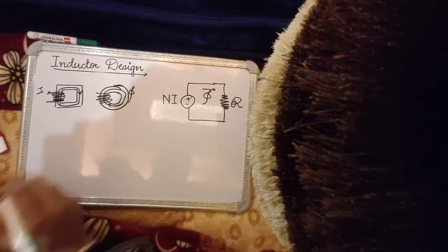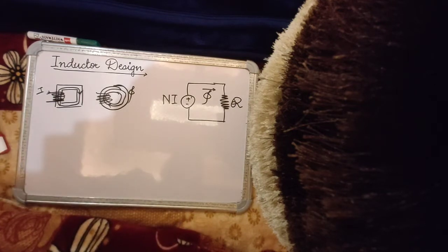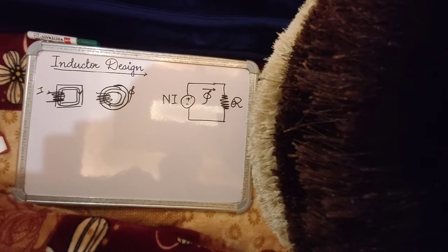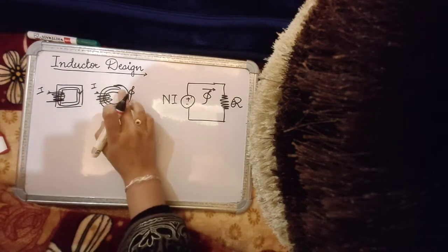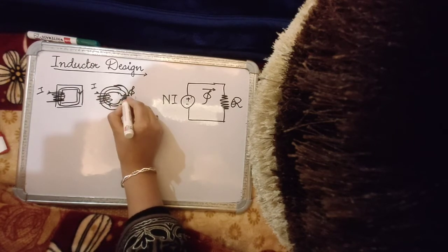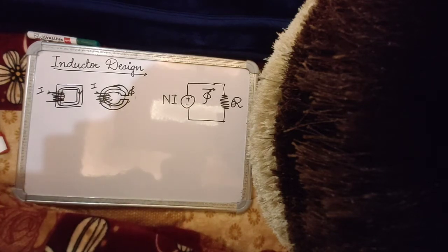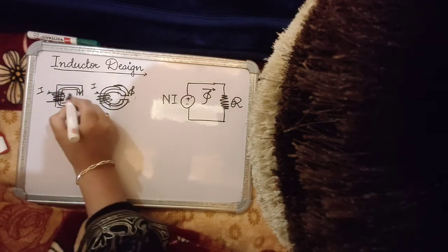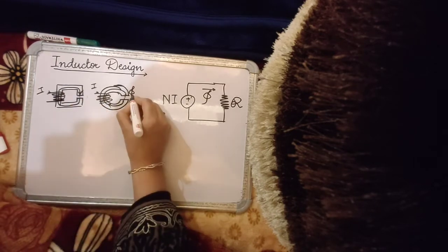So flux is the result or the effect in the circuit, and the opposition to the flow of flux is the reluctance. So these cores offer a very low reluctance path, but because they offer a low reluctance path, it also means that these cores can saturate at very small values of currents flowing through them. To prevent saturation, we often introduce a small air gap within the cores itself. So the flux has to pass through air, which overall increases the effective reluctance of the circuit, and therefore controls or prevents saturation of the core. So generally we have a controllable air gap.